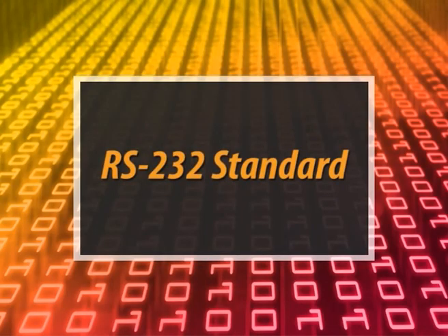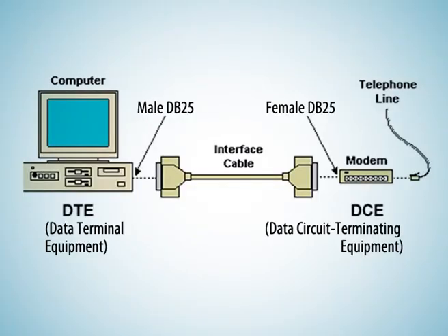This module will cover description of standard for serial interface and UART which implements it. In telecommunications, RS-232C is a standard for serial communication of data. It defines the signals connecting between a DTE, data terminal equipment such as a computer terminal, and a DCE, data